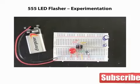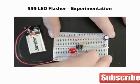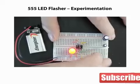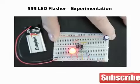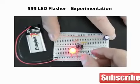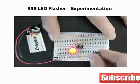Here we have an actual circuit operating with all the components as specified with the 10 microfarad capacitor. Let's try and change the 10 microfarad capacitor for the 1 microfarad. We see after swapping it that indeed the LED does flash a lot quicker. Let's try it with the 100 microfarad capacitor.